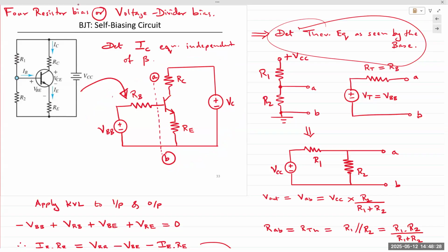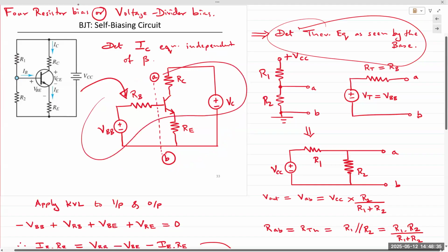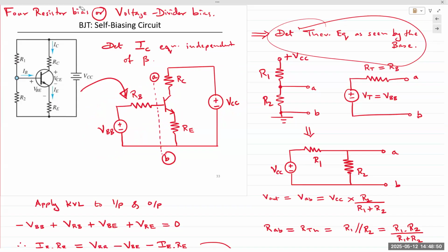Again, the previous circuit was this. So, right? It had a collector resistor, it had a base resistor, it had a collector voltage VCC, and it had a base voltage VBB, 2 power supplies. In this case, we don't have to worry about connecting a second power supply on the base side because the voltage divider network itself creates a voltage that needs to be applied from the VCC.